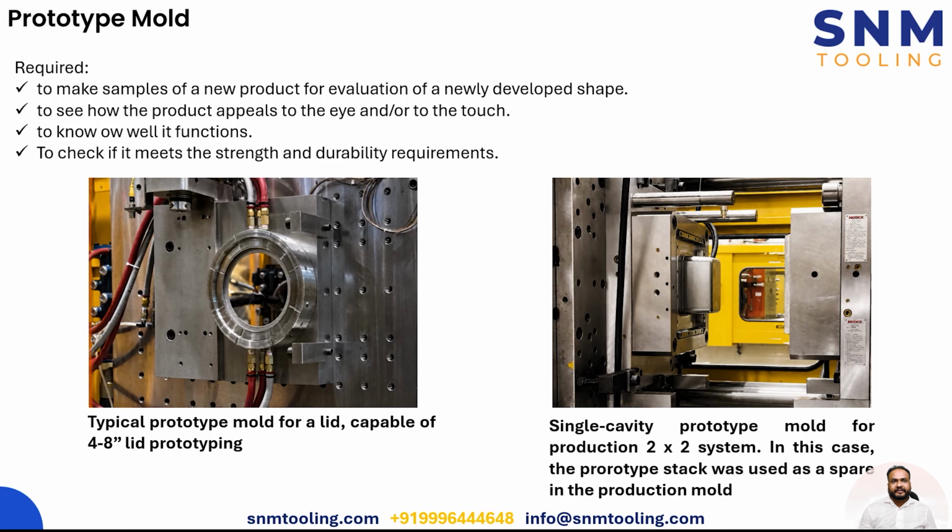Next, the runner system can be just a screw gate directing the flow into the cavity, or it can be a simple runner and an edge gate. And then when the product is ejected, that gate can be cut manually.